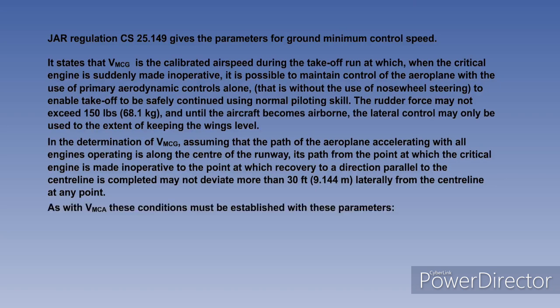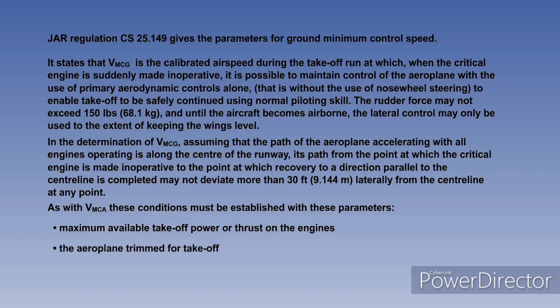As with VMCA, these conditions must be established with maximum available takeoff power or thrust on the engines, the aeroplane trimmed for takeoff, the most unfavourable CG position, and maximum sea level takeoff weight.